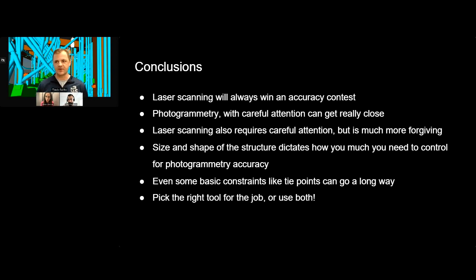That's a whole different comparison, and I think in some cases, the photogrammetry beats the mobile scanners. So in terms of terrestrial scanning, if you're doing any reverse engineering, or if you need to be certain about your measurements, then I would stick with the terrestrial scanning.